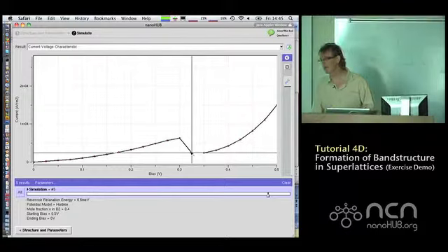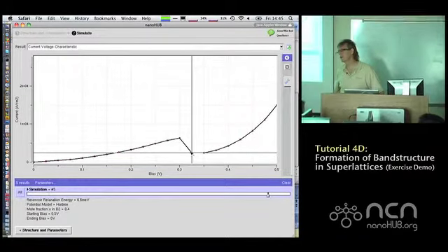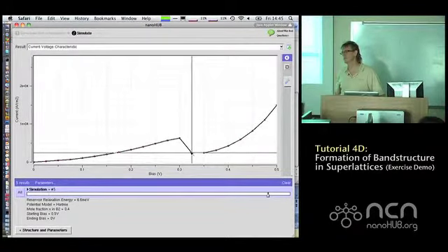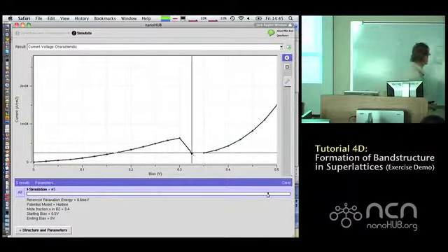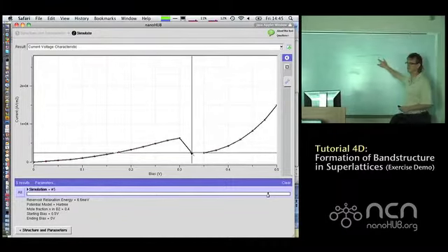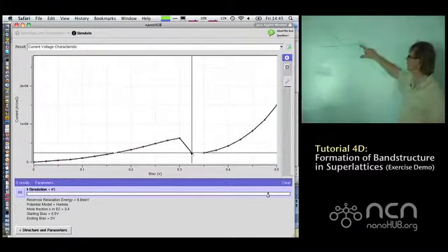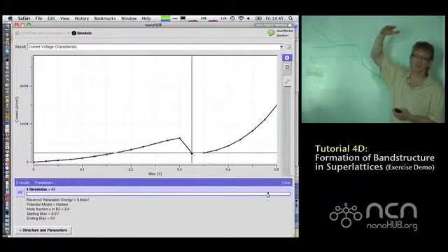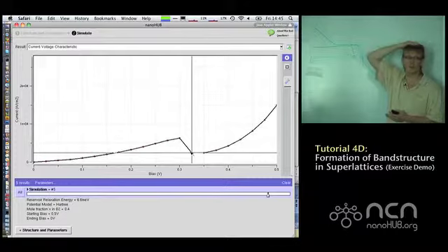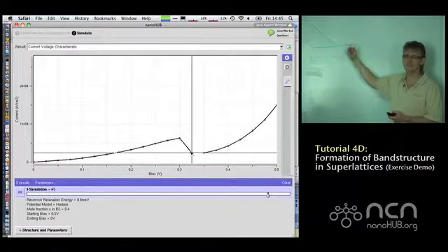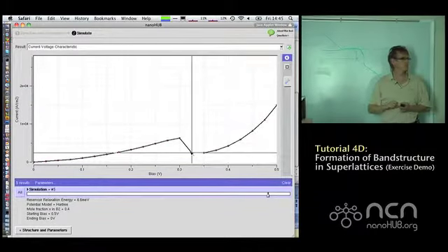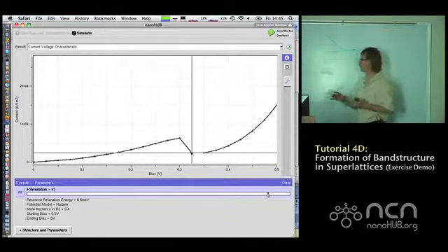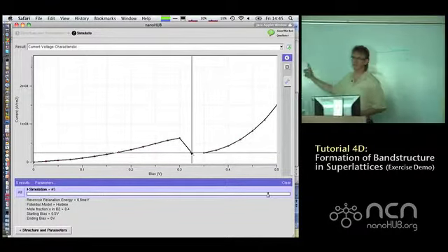Yeah. This is due to the charge in the channel has to go back to the source. No, it's just purely the charge accumulation in the well. The charge accumulation in the well basically would like it to pop out, push the charge up, because it doesn't belong, because there's no doping. Okay? So the well, the notch here has little to do with it.